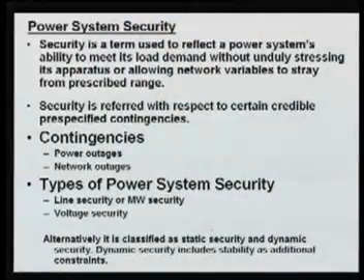Another concern of power system design and operation is your power system security. Security is a term used to reflect a power system's ability to meet its load demand without unduly stressing its apparatus or allowing network variables to stray from the prescribed range. Basically, security is referred with respect to certain credible prescribed contingencies. Again, the contingencies can be of different kinds.